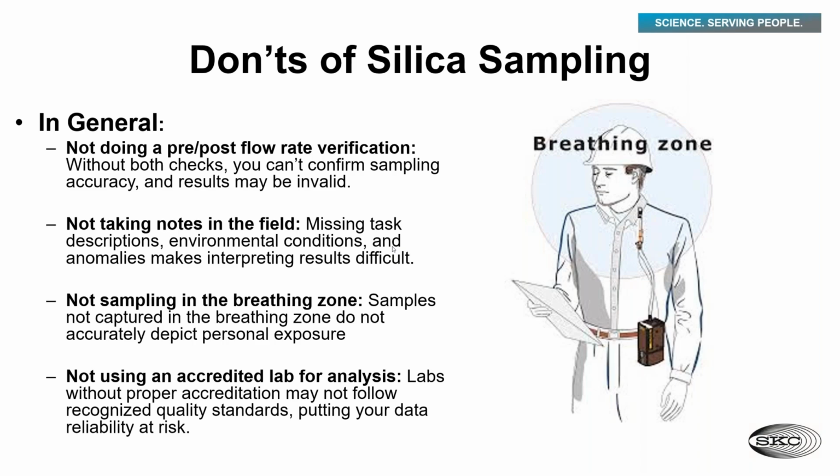And lastly is not using an accredited lab. There are a number of really awesome accredited labs out there in the world that we can use. Do your homework, figure out what lab is accredited and will analyze your sample according to the NIOSH methods or OSHA methods that are going to do a good job. They've been blessed. I can't stress this enough, to be able to use an accredited lab. Don't shortcut yourself to save a couple bucks.